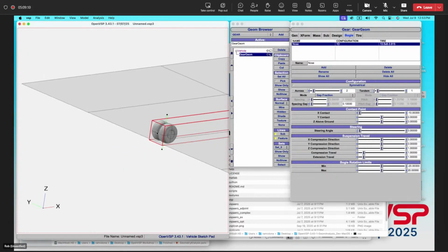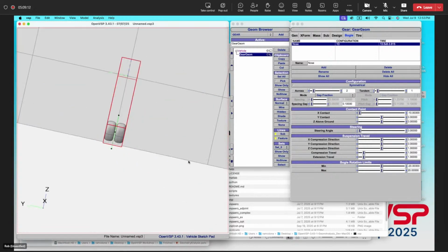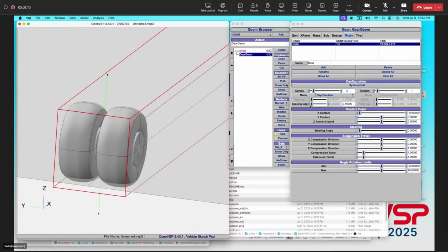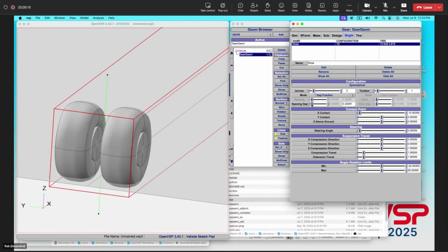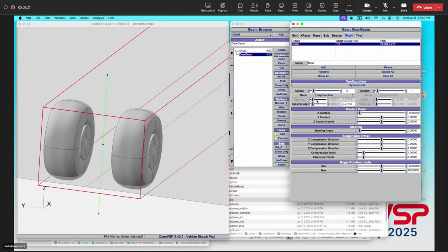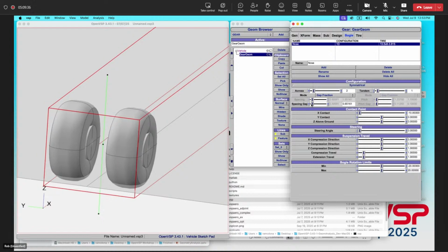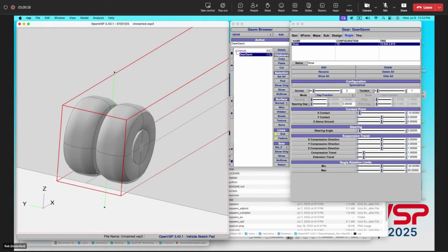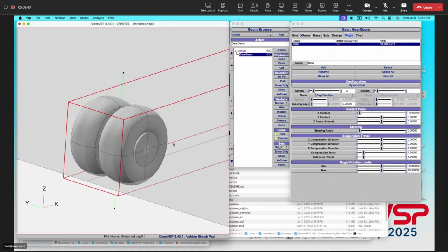And then, like I mentioned earlier, we can either talk about it in terms of the gap, the spacing is a gap. So how far apart are these in terms of a gap? Or, we can do it either fractional or in model dimensions, or we can talk about the center distance. What's essentially the pitch, the distance between centers of these. So, if you're reading off a print, you may have that read off as a center distance or whatever works for you.